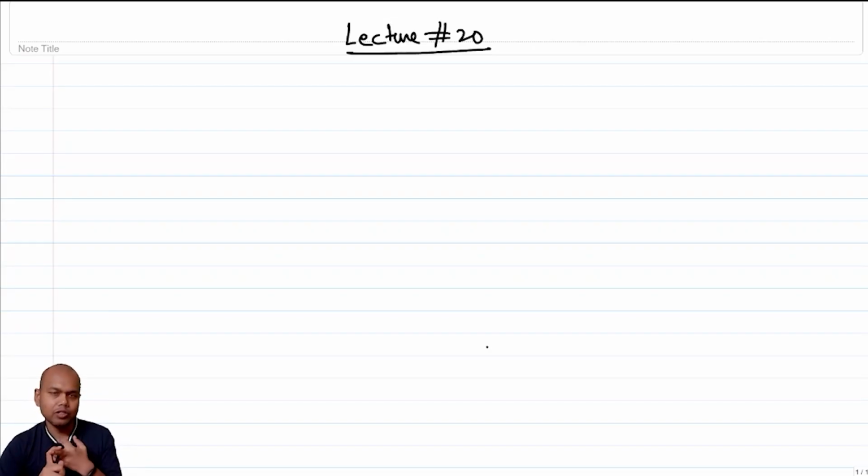So number one, it needs to give matching. The input should be matched to a 50 ohm load. Number two, it should have a good noise figure. What is a good noise figure? We haven't yet defined. Ideally it should be 0 dB, but we know that that's not possible. And number three, definitely it should give some amplification, right? So till now we have dealt with almost all three of them, but in silos. The purpose of this lecture and the next lecture is to combine these effects and then see what are the possible design topologies that we can come up with, right?